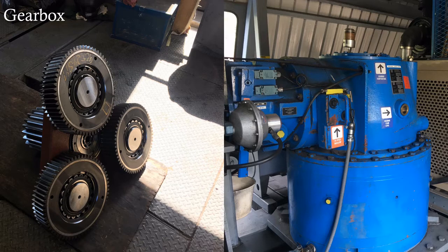Note in this gearbox that power enters from the primary electric mover or auxiliary motor here and leaves to the bull wheel at a higher torque and lower speed here. This gearbox also accomplishes a 90-degree direction change for the power. Gearboxes are a critical component for ropeway systems, both because of the necessary speed reduction for most primary electric motors, and because there is often no good way for redundancy for a gearbox system if it were to fail. Thus, over-engineering is critical for gearbox components. Note the large industrial roller bearings that are used on these gears.